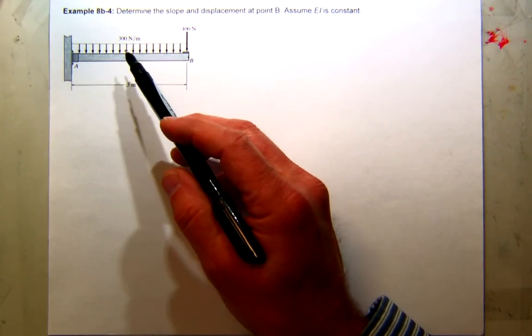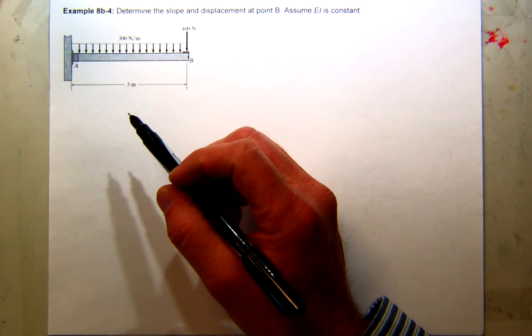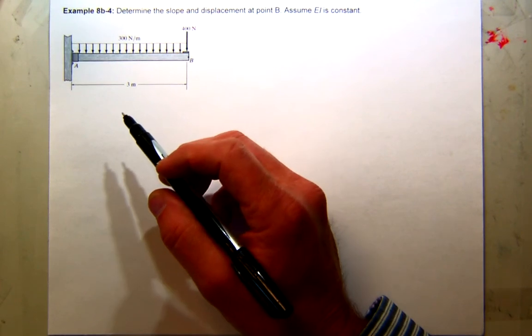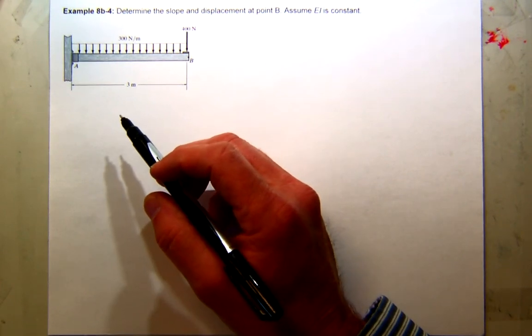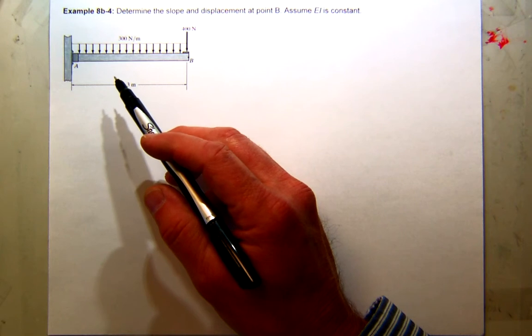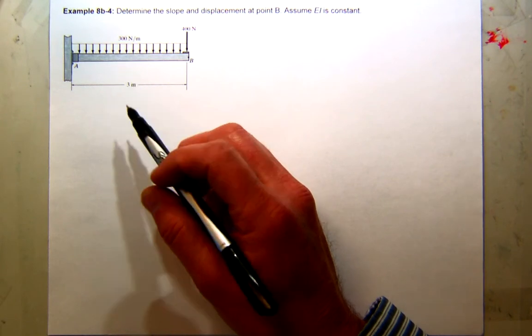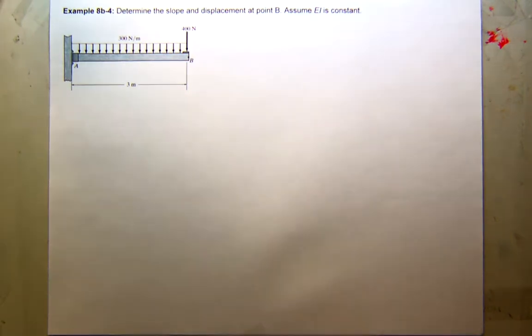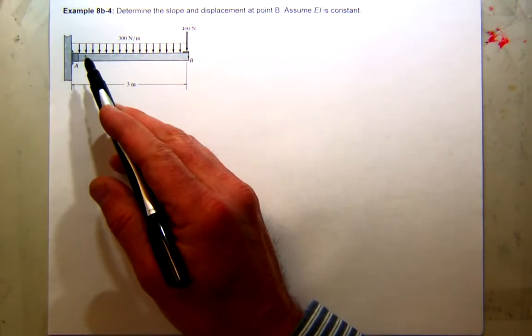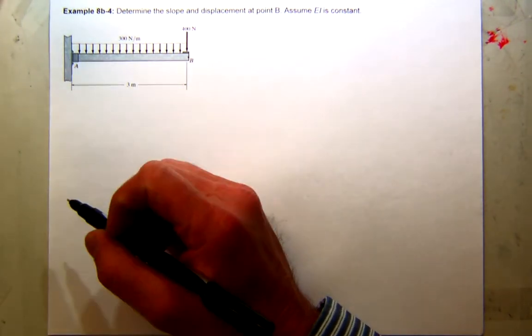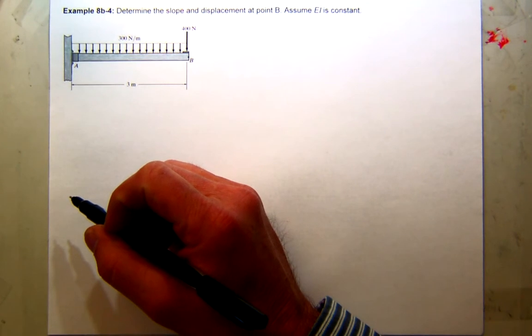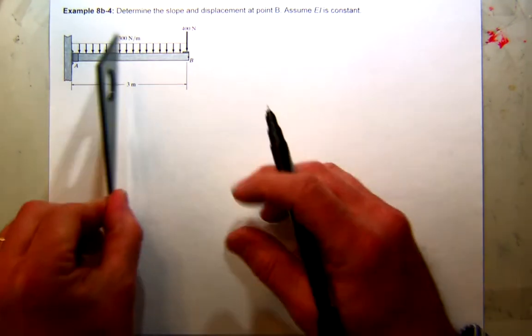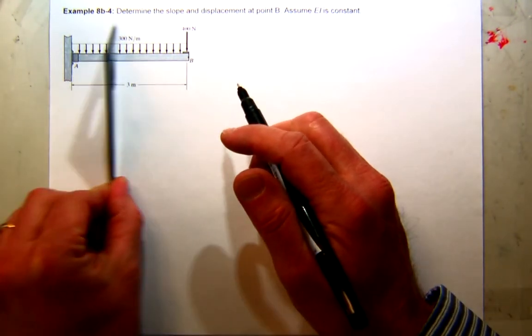But today we'll try virtual work. Now, virtual work does share something with direct integration in that to start virtual work, what do I have to do? Also write an equation for moment, right? So I'm going to do that. So can I write a single moment equation for the real loading that's valid for the whole structure? Answer is yes, right? If I cut it, I can cut it anywhere I want, and you see the load is continuous.